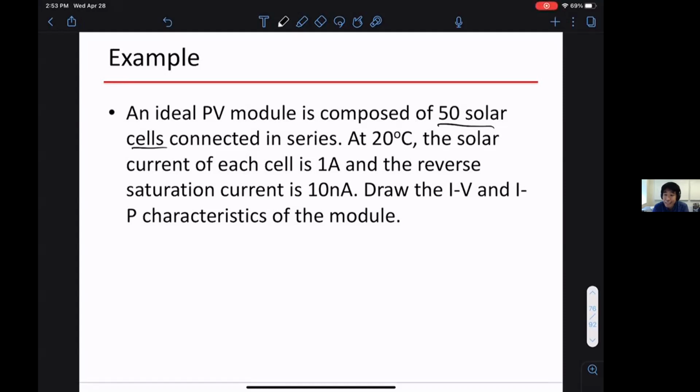Yeah, that's not how it works. So the problem with series connection is you're often limited by the current, by the cell with the least amount of solar current. Just the way the current sources work. So it's not as simple as averaging it out. You're closer sometimes to the least efficient one, or the one that's generating the least current. Because you don't really want to charge your solar cell, right? If you're drawing more current than the solar current is providing, you're basically trying to charge your solar cell. And that's not a good idea.